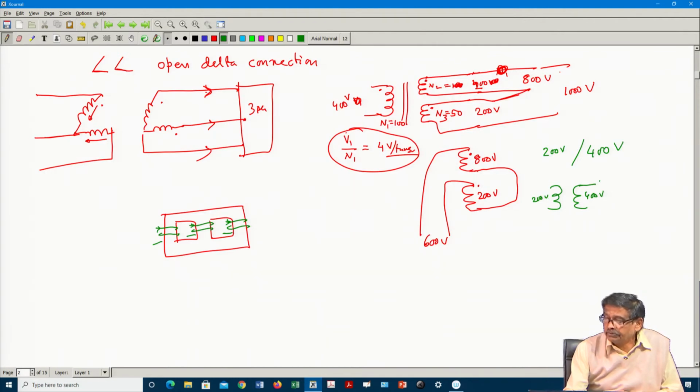Therefore, eventually you are going to connect some load across the secondary of the transformer, and it will drive current. And the moment you say it is driving current, I must know the value of the current, based on which I will decide the cross section area of the wires which make the winding. If somebody says he is going to pass a maximum of 10 ampere current here, suppose 400 volt 10 ampere, that is, he is going to connect 40 ohm impedance here, then 10 ampere will be the current.